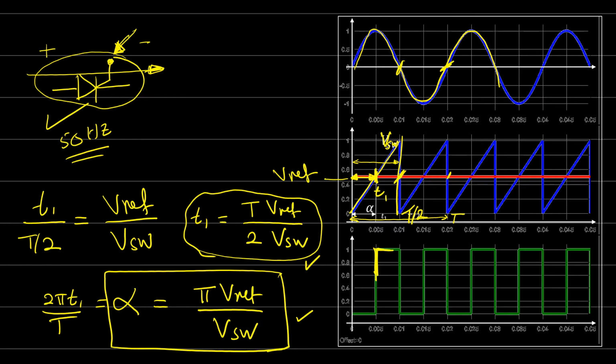Once we send this signal, at this time you'll find that the thyristor starts conducting. Now if we remove the signal, the thyristor will keep conducting. Why? Because it is a huge current. We cannot stop the huge current. There are two ways to stop the thyristor. Either the current inside the thyristor reaches 0, or we reverse the voltage on the thyristor. And sometimes if we still have current inside the thyristor, it will never stop, it will be conducting.